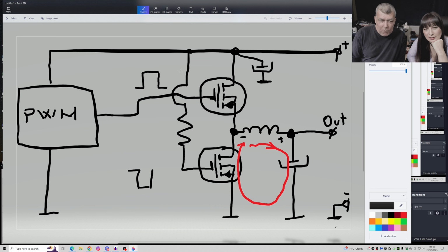So I switch the MOSFET on, but with a resistor here it's always on, because connecting the gate to the plus means this MOSFET will always be on. So how can I switch this MOSFET off then?